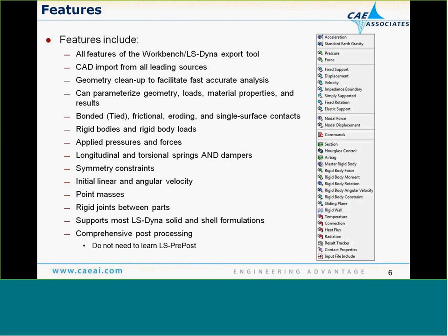You can apply forces and initial velocities, both translational and rotational. You can set longitudinal and torsional springs and dampers. You can apply constraints, point masses, rigid body joints between parts. It also supports most of the Dyna solid and shell formulations, many different shell formulations, for example, that you can now assign within the Workbench environment. And it has a comprehensive set of post-processing tools. You don't need to learn LS-PrePost anymore.